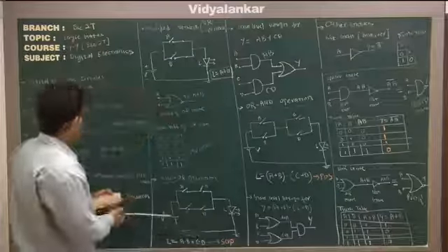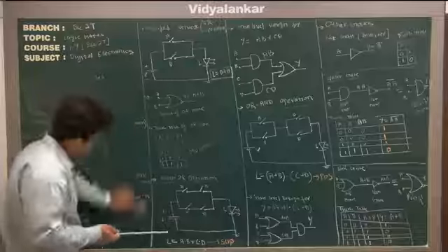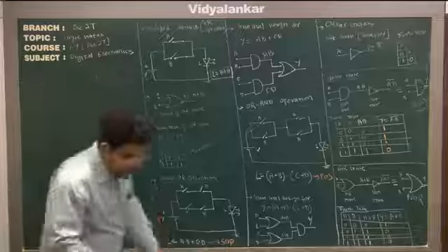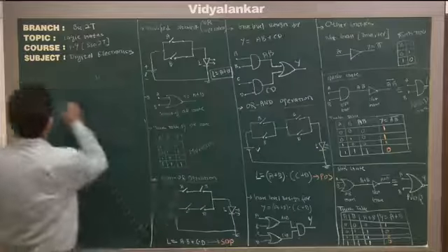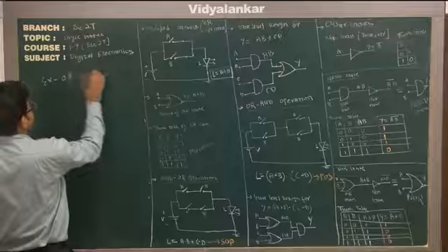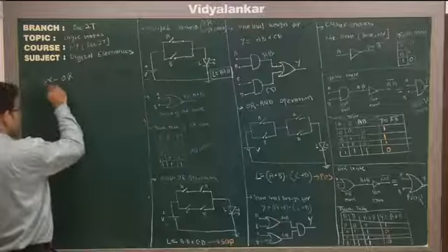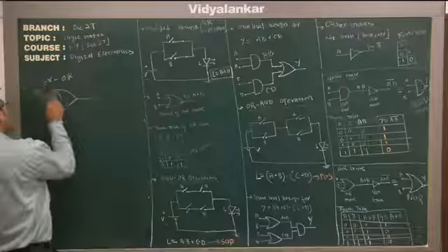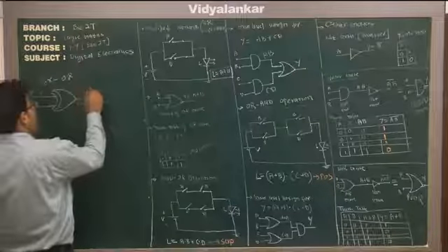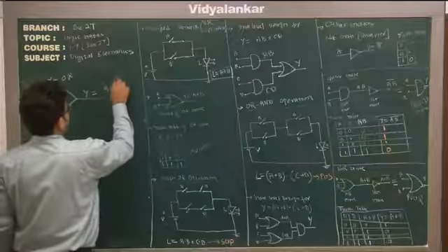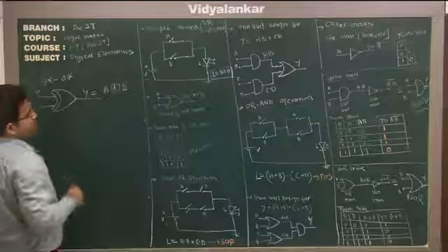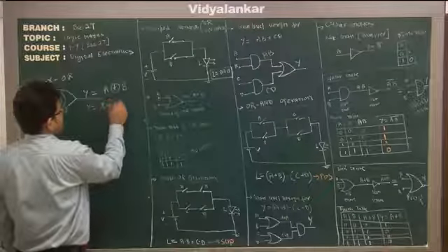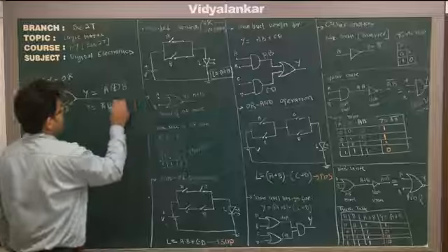And let's first discuss exclusive gates, XOR and XNOR gate. So first in that is XOR gate, exclusive OR. So exclusive OR is like this. 2 inputs again and 1 output Y, and XOR is represented like this. This symbol indicates XOR. Actual expression for this is A bar B plus A B bar.